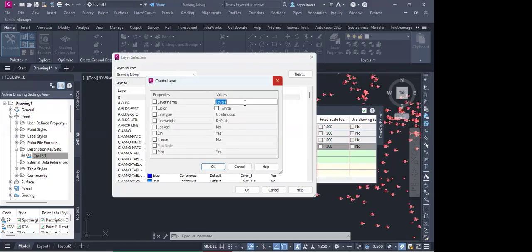And when you're creating a new one, this is a pro tip so that you don't keep on searching for your points. Make sure when you're typing a name, you start with a special character. It might be a hyphen, it might be an asterisk, it might be a number, so that that layer that you create will always appear at the top. You don't go scrolling in between when you're searching for it. So for this case, this is the layer for the spot height.